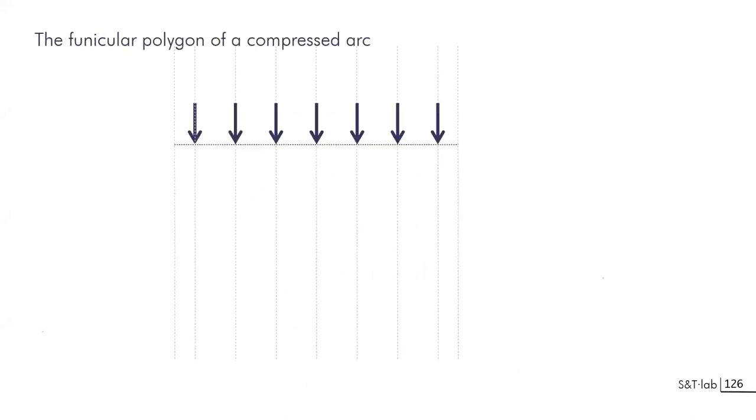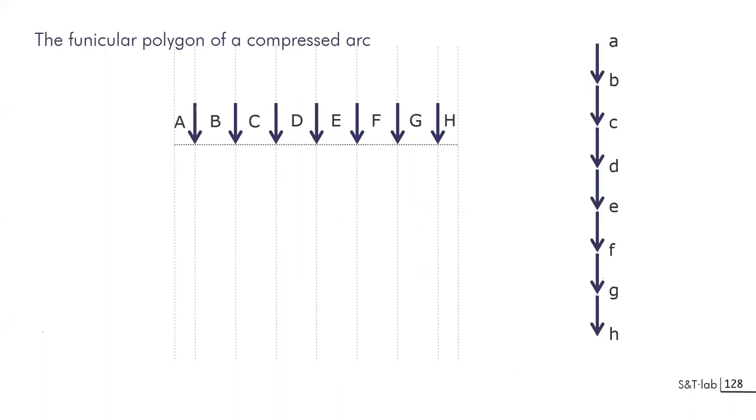What about graphic statics? Graphic statics has been proposed to assess this, and we'll be using the first funicular polygon. So for this, you have to build the load line, as you know already, by denoting and numbering each of the forces on both sides. This is known. And the next step will be that your system will be symmetrical, and you will need to place a pole at the middle of it.